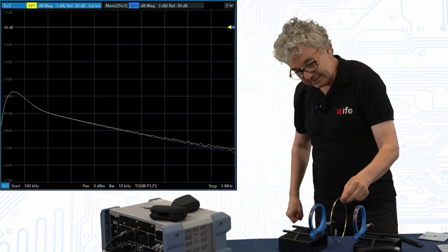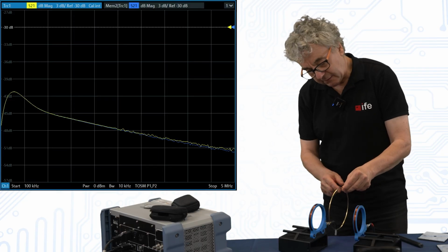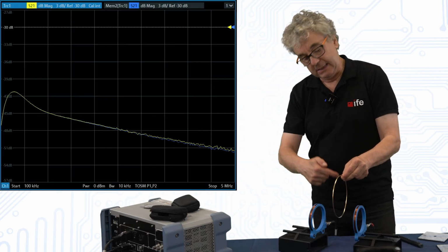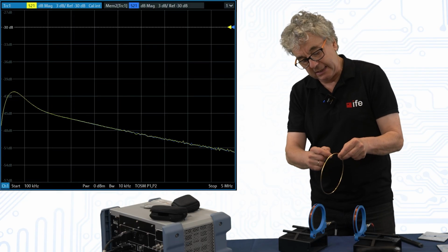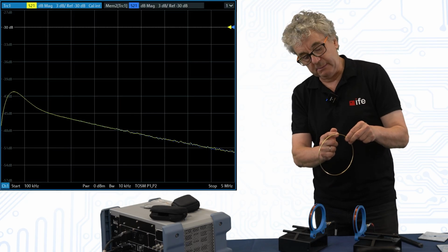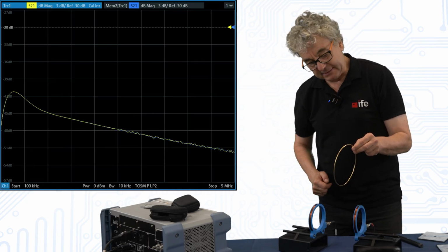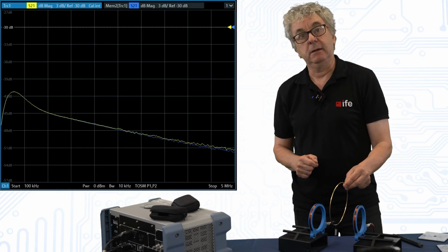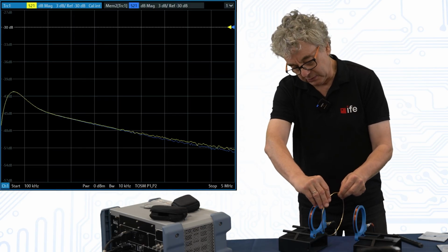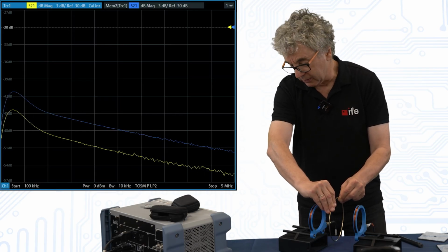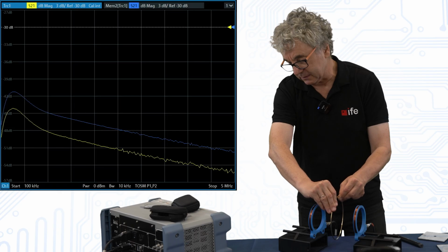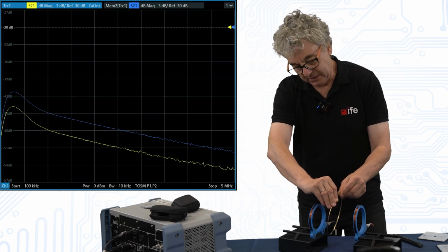What happens? Why doesn't it shield? Well, the magnetic field penetrates the ring, it induces a voltage here, and there's a gap. So there will be a voltage across the gap, but there's no current flowing because there's a gap. If I close the gap, we see the coil reduces the field. Open, close, open, close. So what happens?